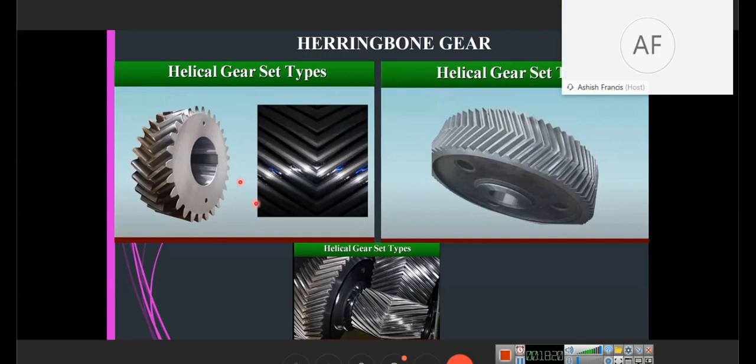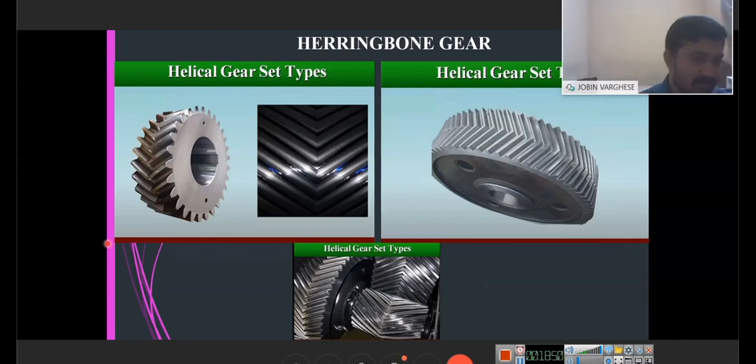Okay, sir. So we can continue with the next session of the 20 minute lecture. The next part is the design procedure of the helical gear. It is similar to that of spur gears, except for some differences in the equations. The helix angle psi is added, so a cos psi factor will always come in when we take the case of helical gears.